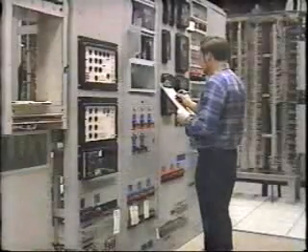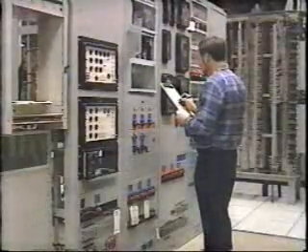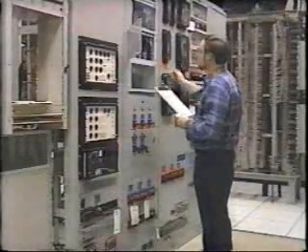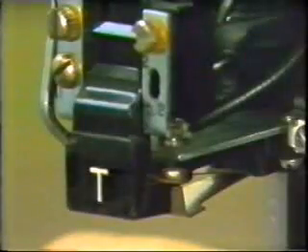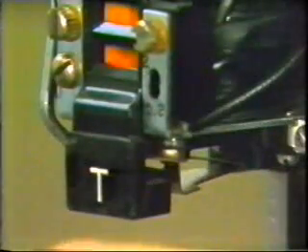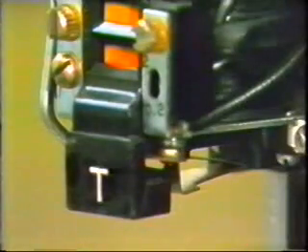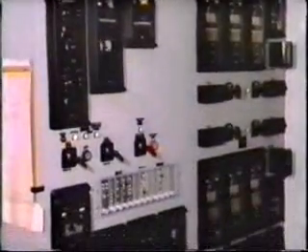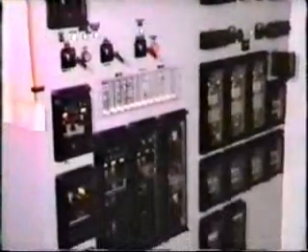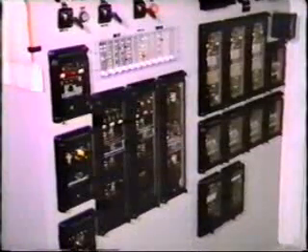Fault data can also be gathered manually. This is done by checking and logging the operation of protective relays. As you know, each relay is equipped with a brightly colored target or flag that tells us when the relay has indeed operated. Such relay actions are always logged for future reference and analysis. Indeed, on distribution systems, this is often the only information which will be available to assist analysis.